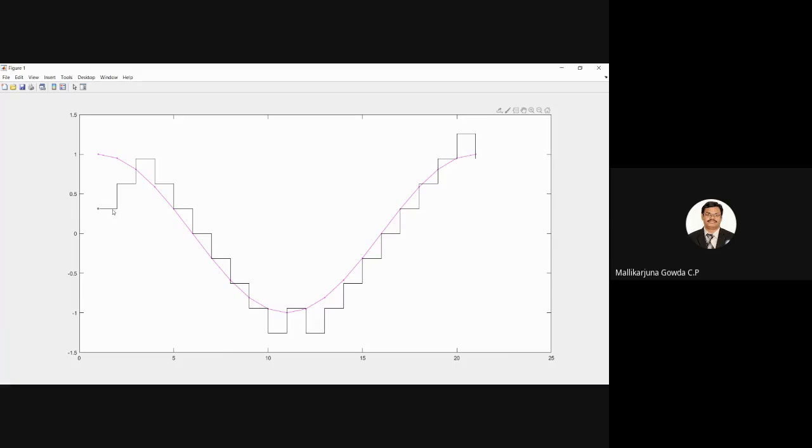See, this is the first sample, right? So it will be incremented by delta, means it will be encoded by binary information 1. Then for the second, 2Ts, still it is less only, means comparator output is more. So it will be again incremented by delta, means it will be encoded by 1, right? At 3Ts, x hat of nTs will be more than x of nTs. So now it will be decremented by delta, right? Yes or no? So I have done this much.